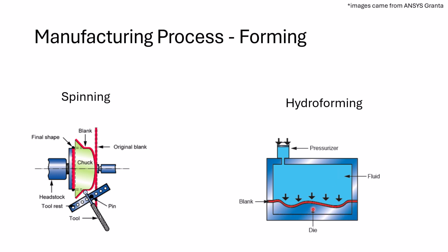So obviously vacuum forming, you can only get so much pounds per square inch, 14 and a half, 15, whatever atmosphere is, where hydroforming you can get much higher ones. I will note though that while this cavity right here is going to be large and big, it maybe doesn't matter as much its surface finish as say for other processes where you're going to have a curve, or you're going to be conforming to the shape of the, I wouldn't say a mold, but it is pretty much a mold. We call it a die here.